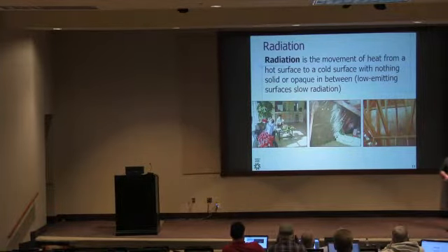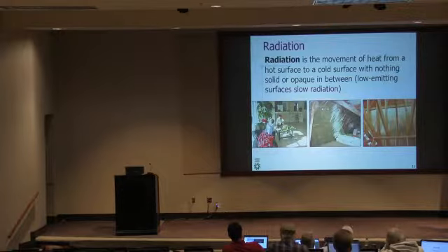That radiant heat transfer. Y'all ever had a house or an office and you had a window in a room that faced west? And you get to be summer and you're in that room with that west-facing window, and what's it feel like in there? It sucks. It's hot. You're just loading up on heat gain, and your system can't keep up with it. It's not designed for the amount of BTUs that are blasting through that window, warming up that particular zone of the house. I think just about everybody's experienced that. August, 3 p.m., west-facing window, that room's going to be pretty uncomfortable because you're getting a ton of heat gain.